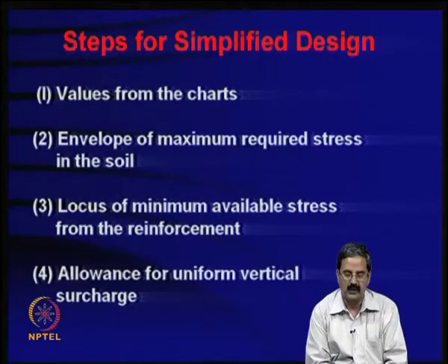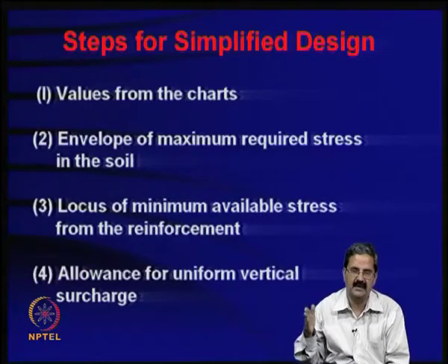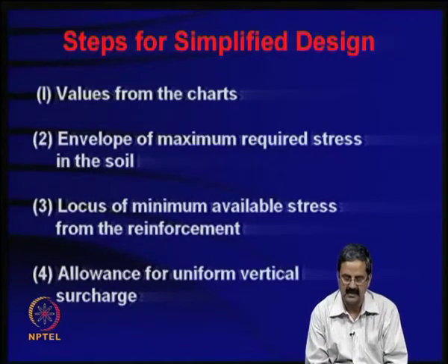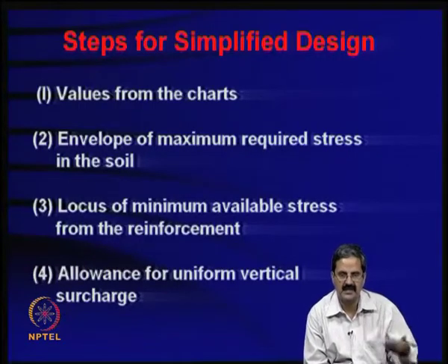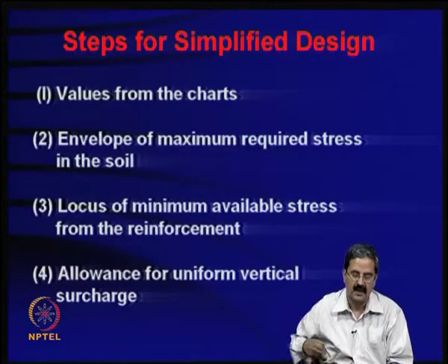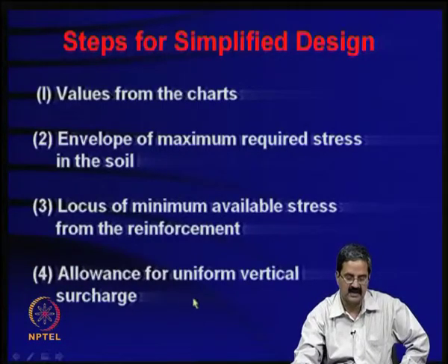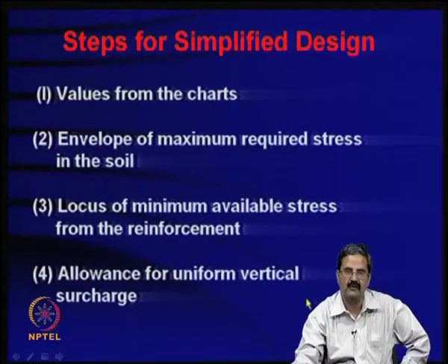What is the reinforcement giving? Something is required, like the earth pressure at any point calculated in terms of Ka gamma H, but what is it that the reinforcement can give? If it is a very stiff reinforcement, it can give inward shear stresses. There is also a surcharge and other things.